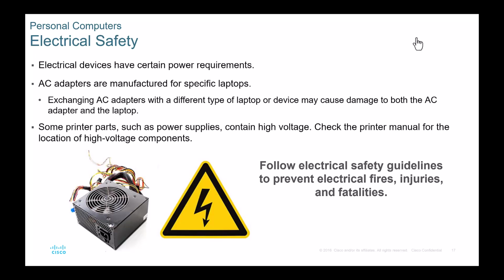Also, when it comes to high voltage, a couple of things you want to look out for, like what devices have the most voltage. CRT monitors from back in the day might be fun to pick up and throw and smash, but they held on to a ton of energy. There were people who did die from messing with CRTs, which I'm glad they're gone. But you will run into them, I promise, at some point in your career.